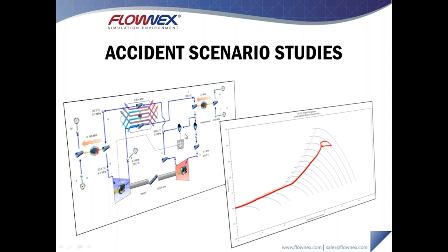We see what we've done in the scenario is put a PID controller to adjust the bypass valve opening based on the surge margin measured in the compressor. In reality, this would be measured more on the pressure ratio across the compressor, or perhaps the actual mass flow through the compressor, and then calculate a surge margin with a small amount of post-processing. Inside Flownex, we fortunately have access to that result, but integrating this into a real control system would just require a small amount of intermediate processing.